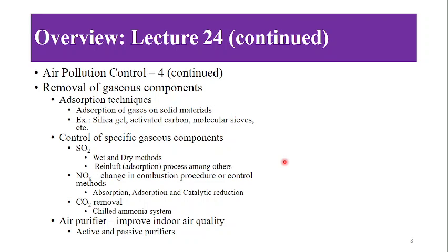But the flip side is that it can also introduce more particulate matter, because exhaust gas may have more particulate matter. So there should be a balance in how much exhaust gas you recirculate, between particulate matter and NOx control.